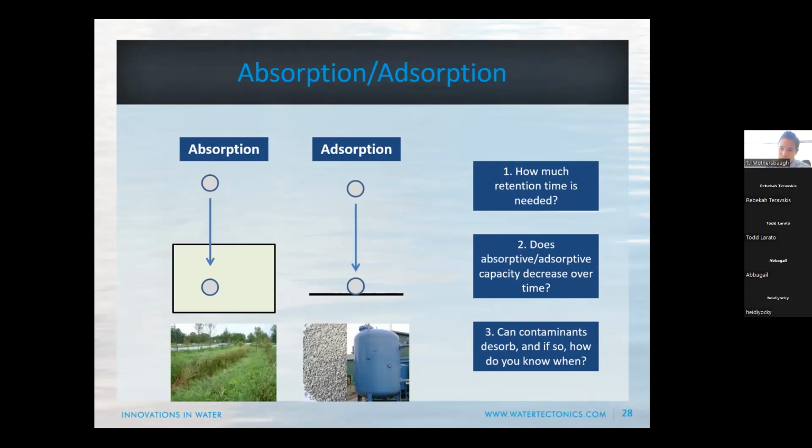And so there are different design standards. I don't really work on the living system side, but on the adsorption side, there are a lot of different design standards, depending on what the target media is, what its capacity to adsorb pollutants is, can they desorb, what flux rates and flow rates do you need, does it want to grab X instead of Y if something else is in the water first. There are all sorts of different design considerations there.